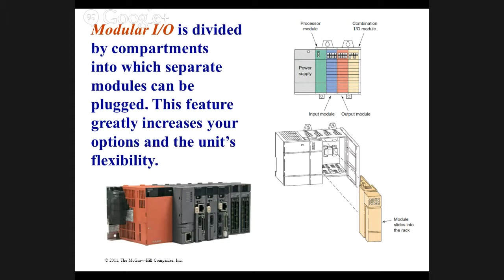Slot 0 in an SLC always takes the processor, and then the succeeding slots take whatever kind of I/O cards you want. You want inputs, outputs, counters, different things.